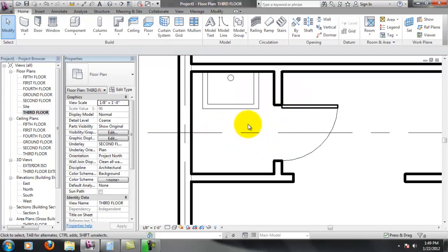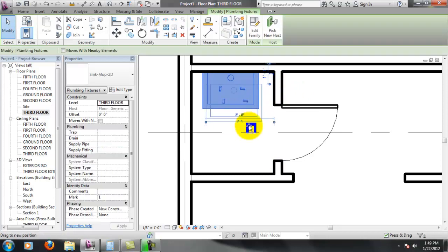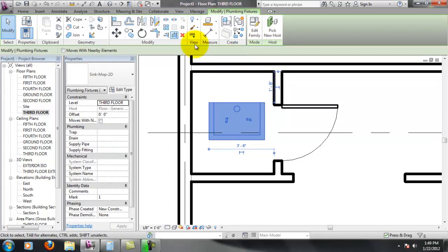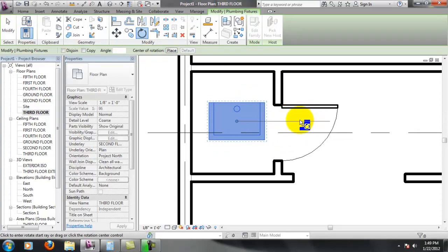So it's saying basically that this sink can go anywhere. Let's see what's going to make the most sense here. It's probably going to make more sense to put some shelving down here. So I'm going to select this guy again and go to my rotate command. Remember, I have this object selected, so notice the green. The green represents that anything that can modify this is going to be green. This green line covers this rotate. Now to use the rotate, you select the angle that you want to base it off of.